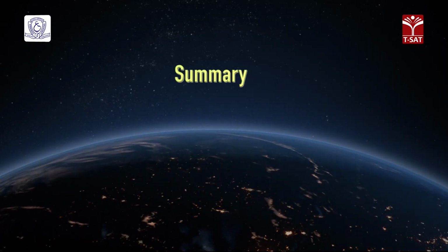Used with traditional GNSS systems, it pushes the accuracy of position to centimetric precision and to millimetric precision for altimetric applications and also allows monitoring very tiny seasonal changes of Earth rotation and deformation, in order to build a much more precise geodesic reference system. Global Positioning System, United States.